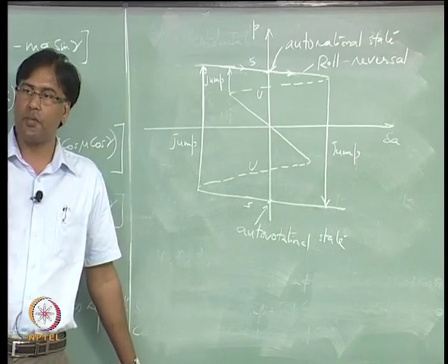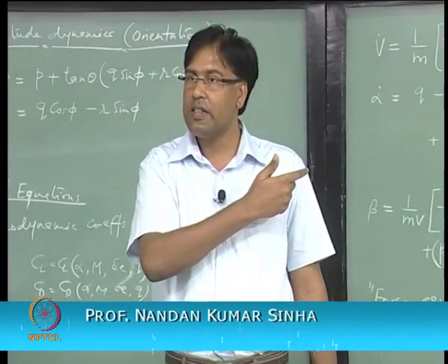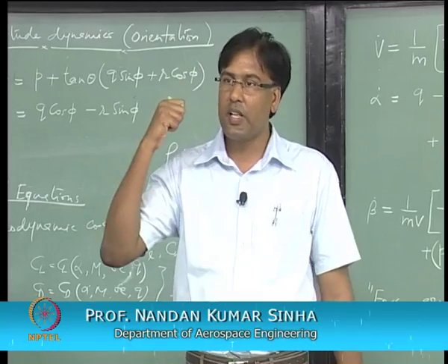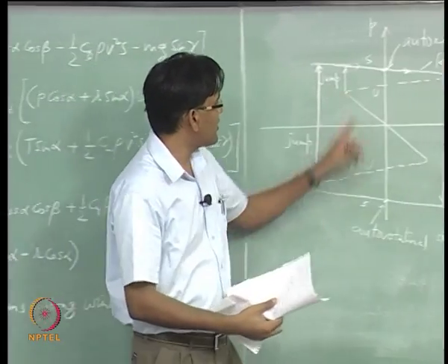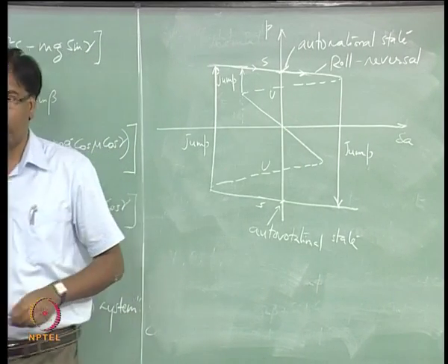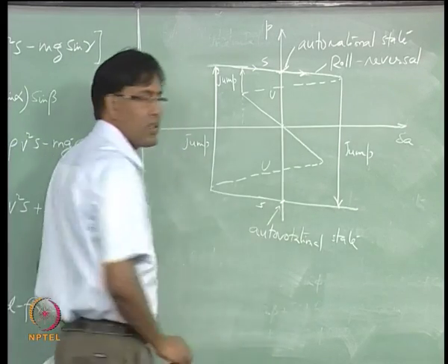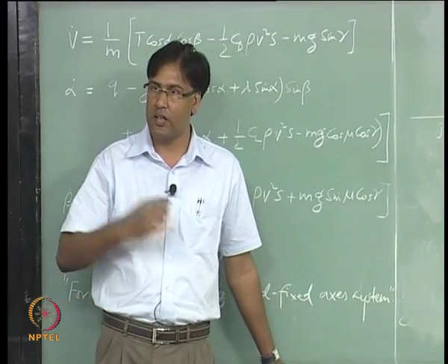Now, unless you do something else to kill that side slip, and not really killing the roll rate, right. So, you have to kill the side slip using rudder to bring your aircraft back to this 0 roll rate condition. So, using aileron and rudder both together it is possible to bring your aircraft back to 0 roll rate, right, but not using aileron alone.